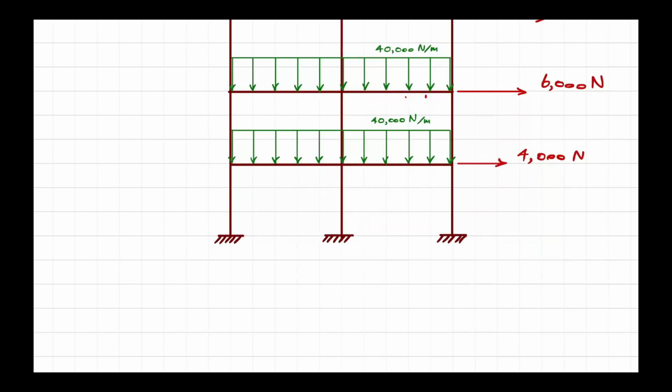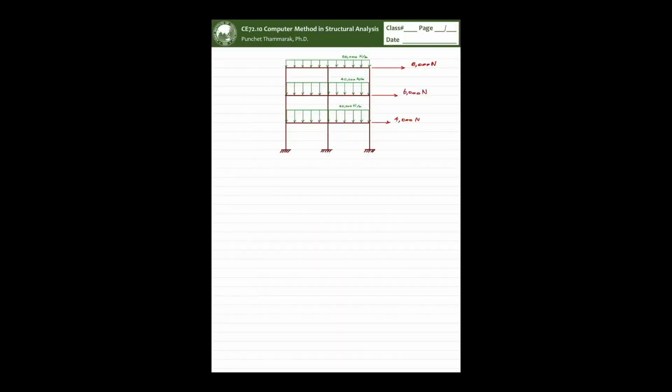And the best thing when you're going to use the program and you are not sure about how this thing behaves in the program, just come back to the basics. Construct a very simple structural element that you understand the behavior quite well. It could be a part of a 40-story building that you are designing, but you don't really have to test the idea or test the module of the program or the input somewhere in that program that you are not so sure about. Test it in that 40-story building, because the response is so complicated.